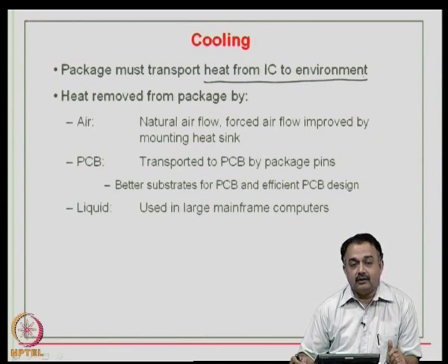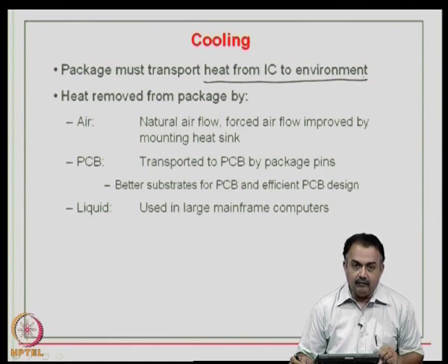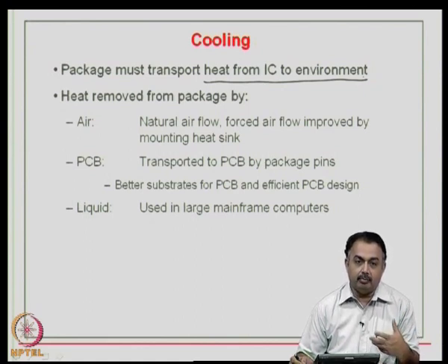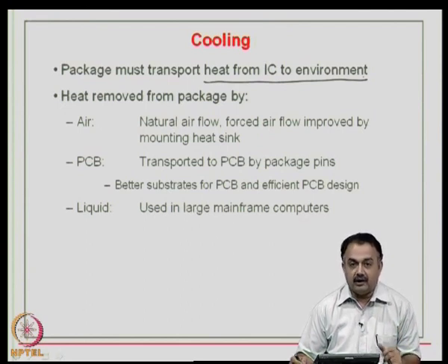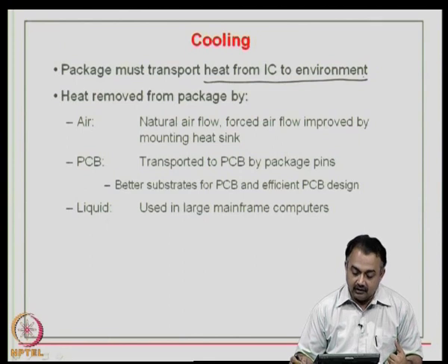because if you look at the previous classes, what we have discussed, when heat emanates from a die, when we power up a particular circuit, there is a silicon die, and if there is a heat buildup, there can be die crack because of heat accumulation, and there can be fatigue on the interconnect structures.